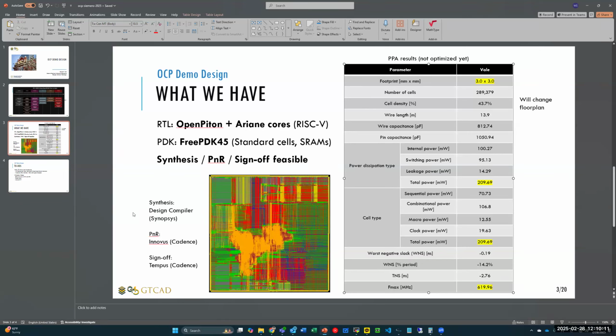It's going to look reasonable. With 2 by 2, we should be able to place, if the CPU chiplet is 10 by 10, 4 CPU instances in 10 millimeters. Or we can make the chiplet 11 by 11 if we need to, add 4 by 4, 16 CPU cores, and call it a 16 CPU chiplet.